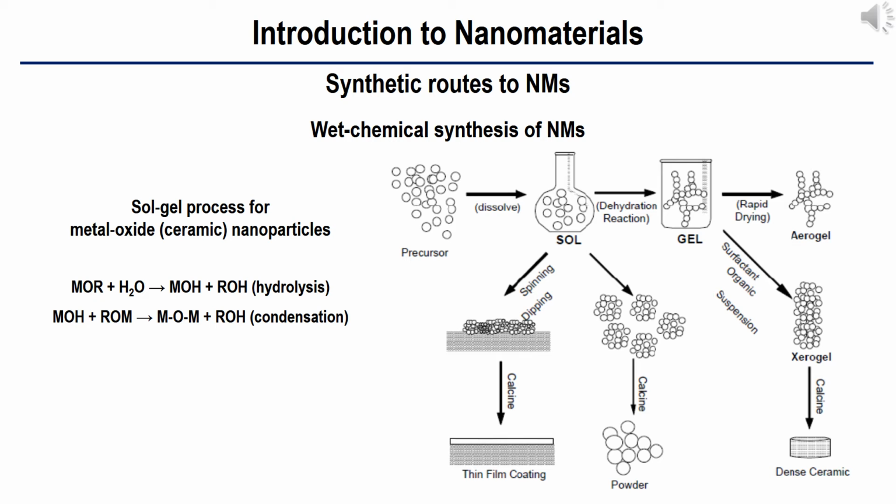2. Gelation resulting from the formation of an oxide or alcohol bridge gel network by a polycondensation reaction that results in a dramatic increase in the viscosity of the solution. 3. Aging of the gel, during which the polycondensation reactions continue until the gel transforms into a solid mass, accompanied by contraction of the gel network and expulsion of solvent from gel pores.